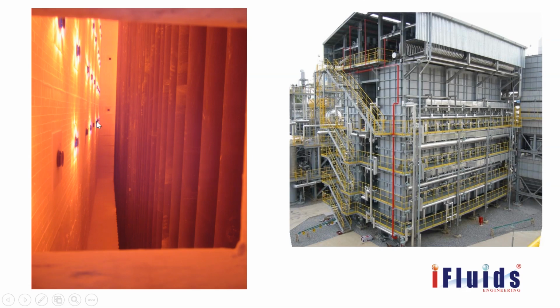This is the picture of a reformer when it is online. All the glowing lights on this side are the burners, which are in fire. The flame should not hit the tubes directly, because impingement of flame will deform the metallurgy and weaken the tube. To avoid that, the flame travels sideways along the refractories. The heat is radiated to the tubes, and from the tube wall it is further transferred to the catalyst and the feedstock. The outer structure of the reformer looks like a big building, whereas inside are the vertical tubes.